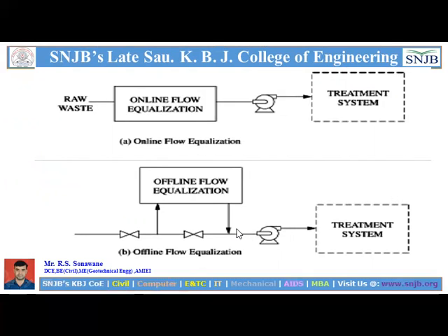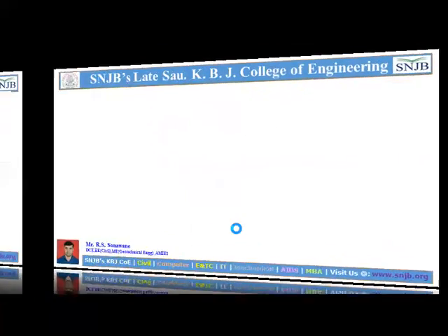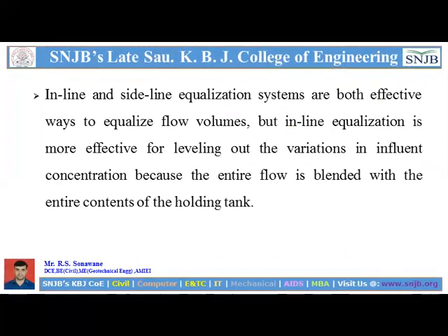So you can understand very well through this picture. And now we will see shortly that inline and sideline equalization systems are both effective to equalize flow volume, but inline equalization is more effective at leveling out variation in the effluent concentration, because the entire flow is blended, as we just saw in the previous slide.